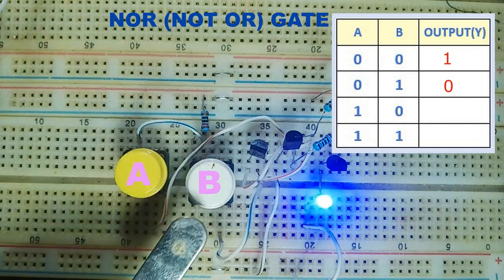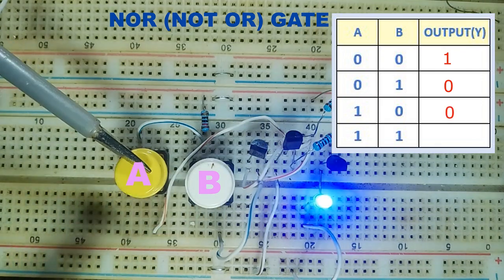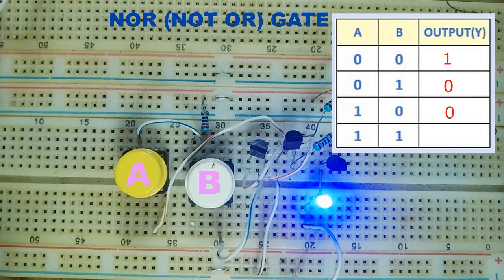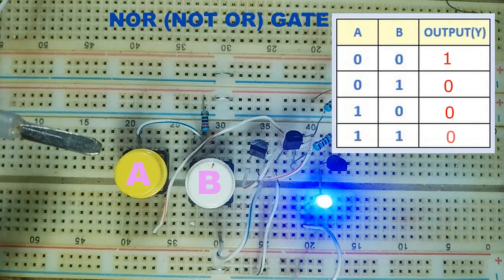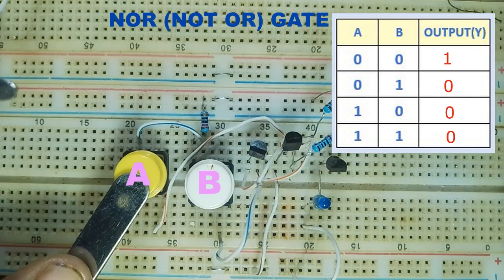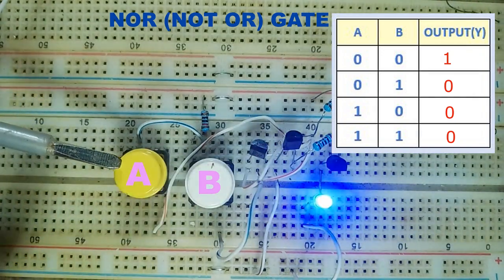Pressing A turns off the LED, and the same result occurs when B is pressed. Again, let's add the 2 states to the truth table. Lastly, let's press both A and B to see the result. The LED turns off, an indication of logic 0. A completed truth table shows a complete inversion of the OR gate, which is what you can achieve with a NOR gate.